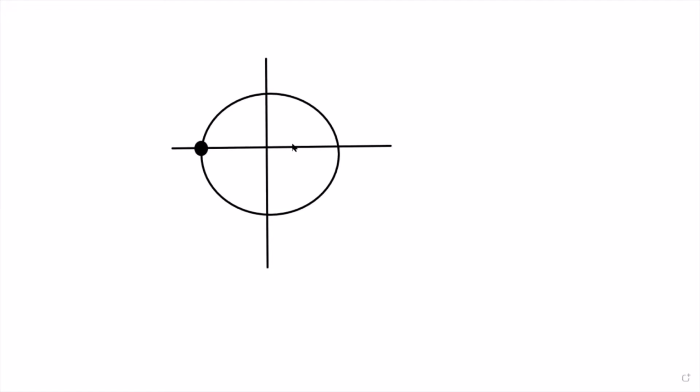That gives you flexibility. You can easily implement different ideal IIR low pass filters using this first order filter by simply changing the location of this pole. You can put this pole value here, here or here, but make sure this alpha value, the pole position, is less than 1.